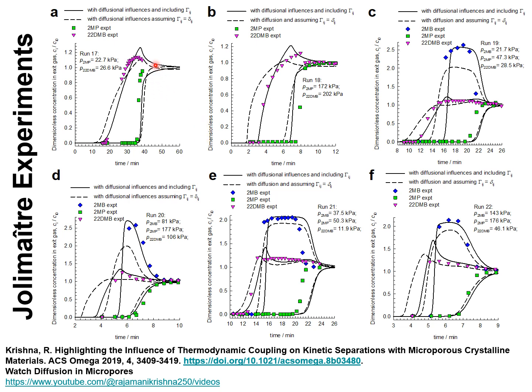The continuous black lines are the simulations using the Maxwell Stefan formulations, including thermodynamic coupling. The dashed lines are the simulations using a simplified model, say the LDF approximation, based on Fick's law, in which thermodynamic coupling influences are considered to be negligible.